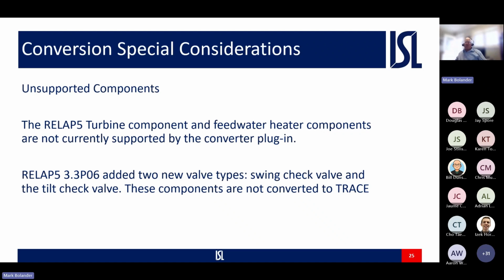The RELAP5 turbine component and feed water heater components aren't currently supported by the converter plug-in, so you want to be wary of that. In fact, when you go to convert your RELAP5 model, in that dialog box, you can select or deselect the components that you want converted over.